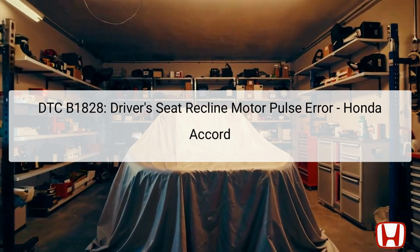The DTC code B1828 indicates a malfunction related to the driver's seat recline motor pulse in Honda Accord models from 2008 to 2012. This error specifically occurs when the recline switch is activated for more than 1 second as the seat reaches its forward or backward limits.